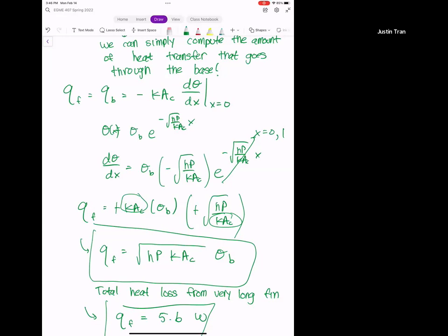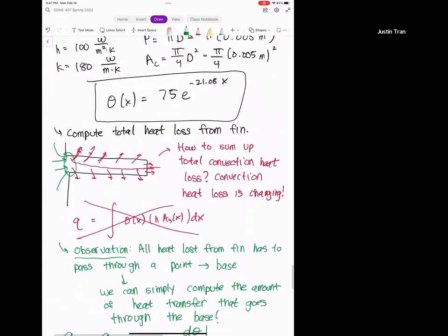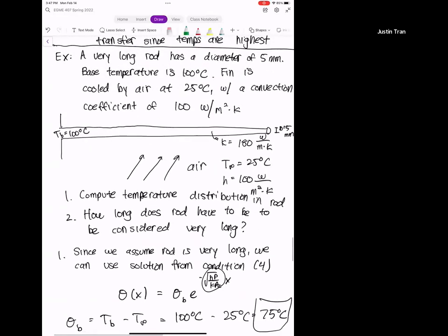Yeah. No, right. So for a fin, the conduction heat transfer is just the heat transfer down the length of the fin. Right. And so if you think of what we just talked about, all the heat that's coming to the fin is coming in from the base, right? Okay. And so some of that heat's going to get lost to convection, right? So that just immediately exits the stage, right? But then some of that is going to travel down the length of the fin as well. And so that's why we call it conduction heat transfer. So that's the heat that's actually traveling down the solid part of the fin. I mean, eventually all of it's going to be lost to the fluid, but you can almost think of it as a two branching path.